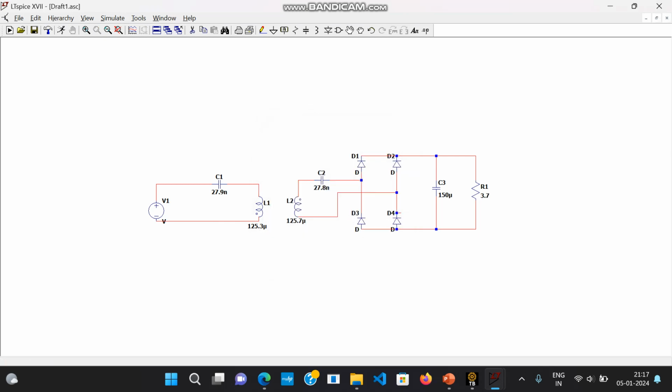Now we know that these two circuits are wirelessly connected, but how will the system know that they are connected, though not physically by wire? For that we use a SPICE directive.